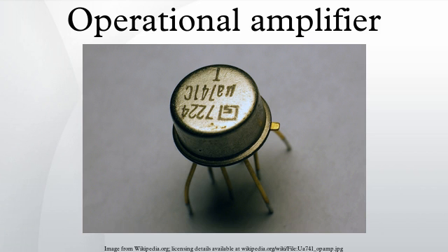In the non-inverting amplifier on the right, the presence of negative feedback via the voltage divider Rf, Rg determines the closed-loop gain ACL equals Vout/Vin. Equilibrium will be established when Vout is just sufficient to reach around and pull the inverting input to the same voltage as Vin. The voltage gain of the entire circuit is thus 1 + Rf/Rg.